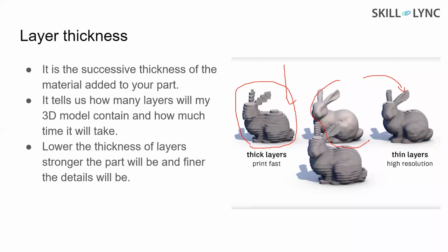In this particular case, our layer thicknesses are very fine, maybe in the range of 0.05 mm to 0.15 mm. Then your model will be highly clear, a highly finished model. But the problem is that when you have such a small layer thickness, it'll take a lot of time. And one important factor: when you have a very good layer thickness, in the sense of very thin layers, the strength of your model will be much more than with thick layers. Why? Because you have many more layers to withstand the load. So that's about your layer thickness.